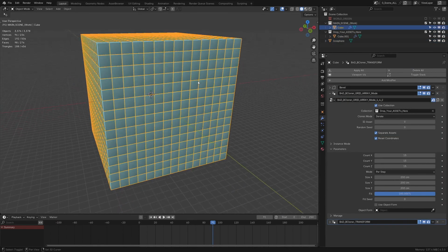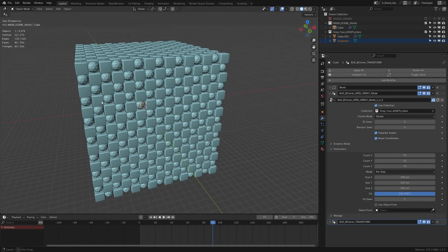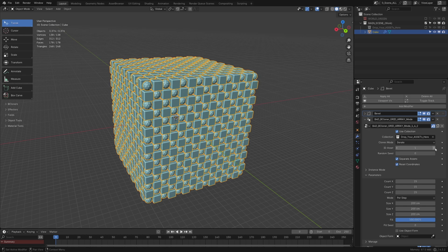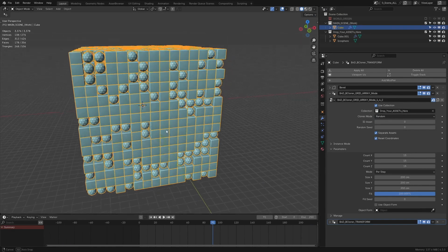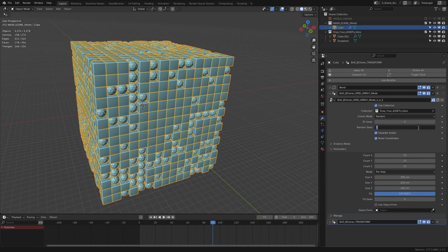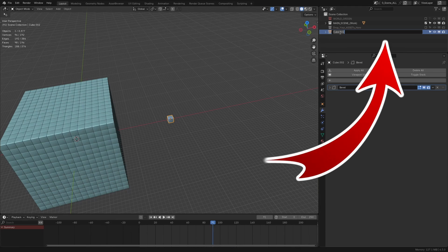In this mode, the instances will be created in the order of the objects added in the Drop Your Assets Here collection. You can change the order using the ID asset parameter. In the random mode, the cloned objects will be placed randomly, and you can change the random value with the random seed parameter. These two modes are the most used, the rest are more complex for specific cases. You can check the video documentation for more details.